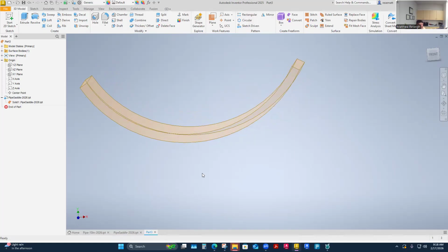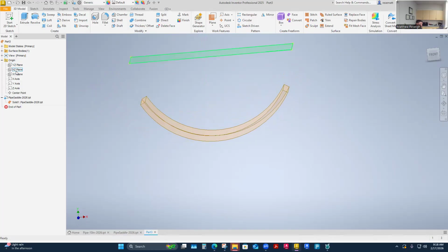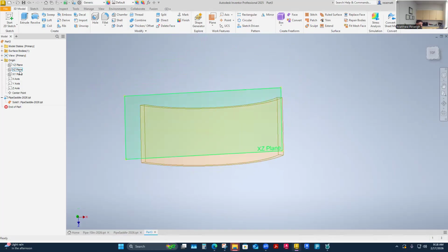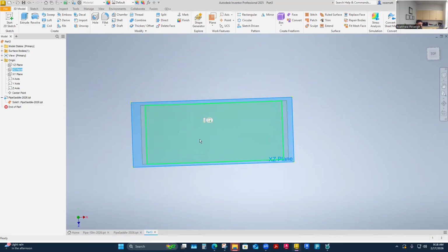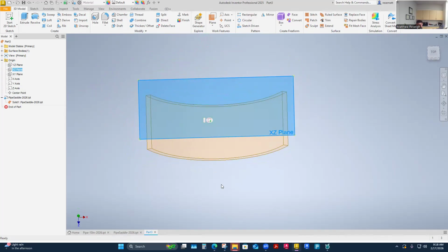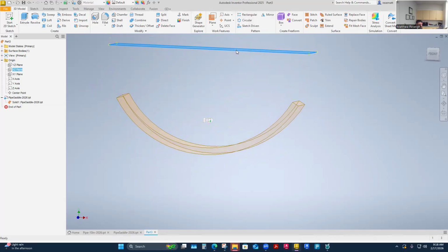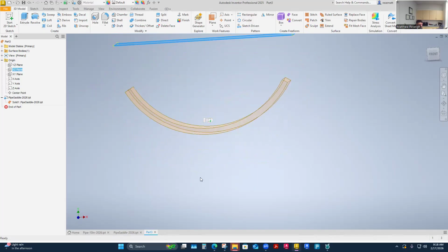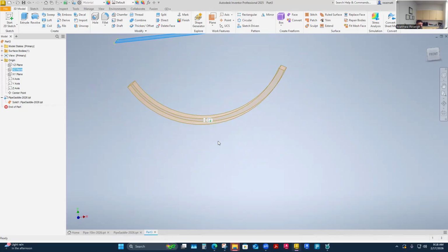And that might work pretty good. I could also draw that pipe profile, because I think what I'm going to do is draw it as this ID and OD circle like I did with that first pipe, and then just extrude it how long I need it. If I started that sketch here, I'd be extruding through and then I'd be cutting it off where it goes through the saddle.